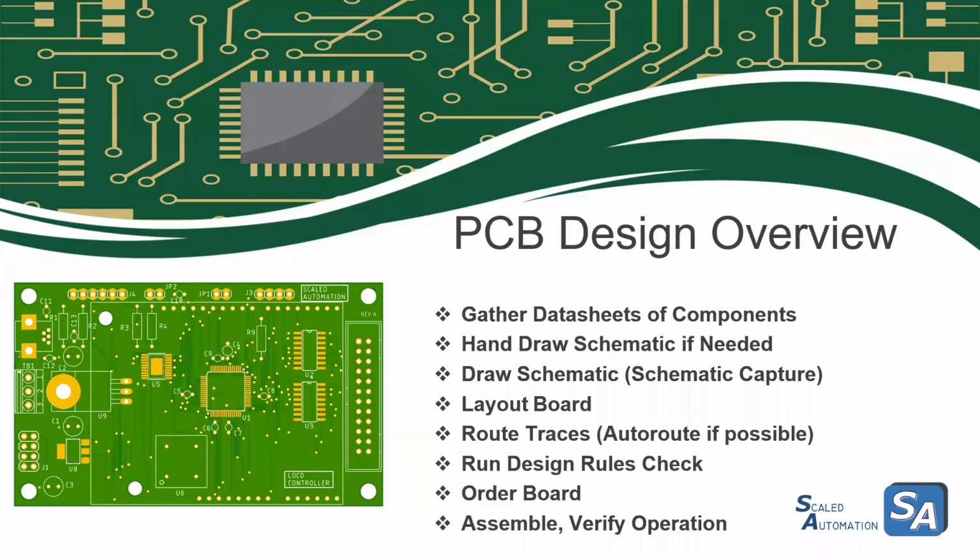So printed circuit board design overview. You're going to gather data sheets of components. We'll see that a little bit later today. Hand draw a schematic if you need to. If you're pretty familiar with schematics, you may not have to. You may have a reference schematic you're starting from. Then in Eagle, we're going to draw the schematic, and that's sometimes called schematic capture. We're going to put that schematic into Eagle. During that phase is where we're going to start interfacing with libraries, and you'll see that when we work through this. Once the schematic is done, or at least mostly done, we can start laying out the board.